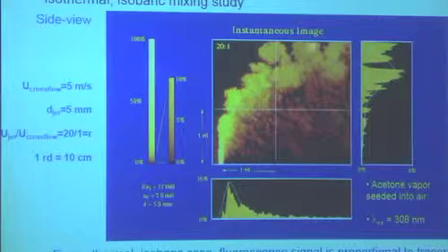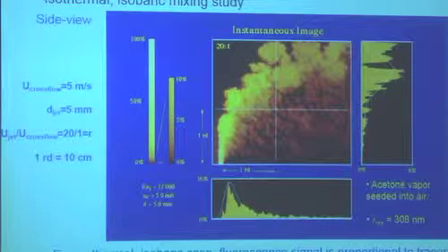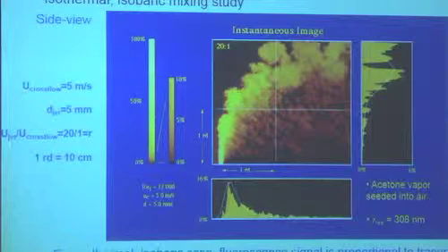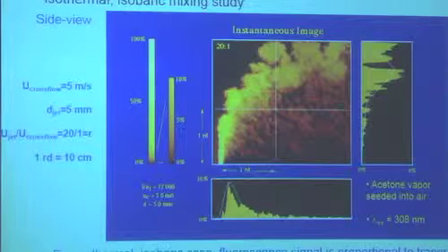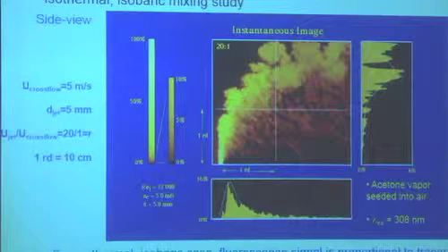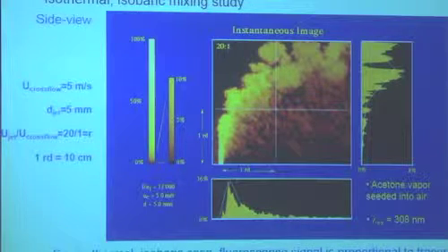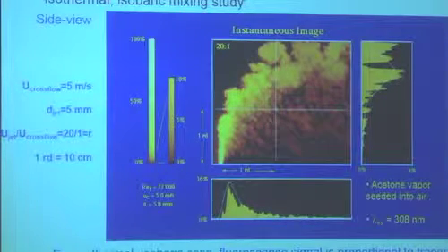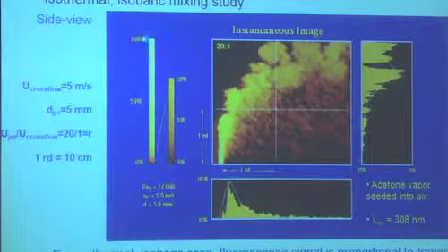And this is a single shot image in the central plane of the jet of what is therefore going to be the mixture fraction. So it's isothermal, it's isobaric, it's slow speed, essentially incompressible, tailor-made for this rig. This laser had no knobs. This camera had no knobs. He just turned them on, formed it into a sheet, took pictures. Because this is an unintensified camera, it has huge dynamic range. So in this picture, where this is the intensity distribution, we had a very wide dynamic range.